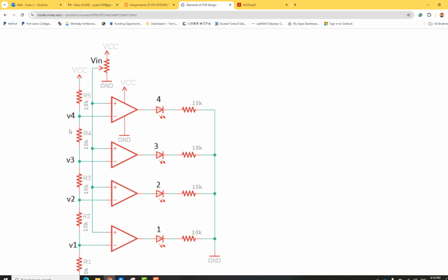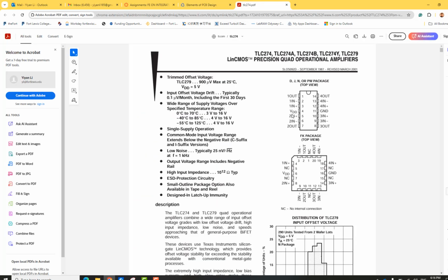The first time I heard that the op-amp was not available, and we have this one available here. So when you get a new op-amp, what's the first thing you want to look at? Gain. Yeah, we are using the infinite open loop gain. As long as they are sold by a decent company, it should be infinite open loop gain. That's one of the things we want to look at. But for this lab specifically, how many op-amps are on the chip? That's another thing we want to look at. That's good. Anything else?